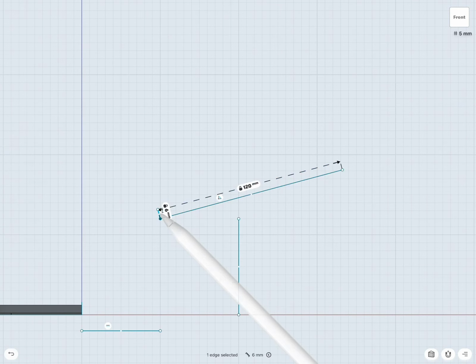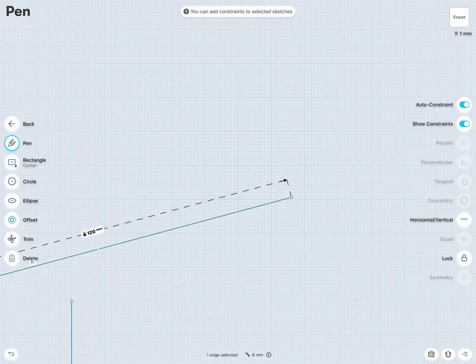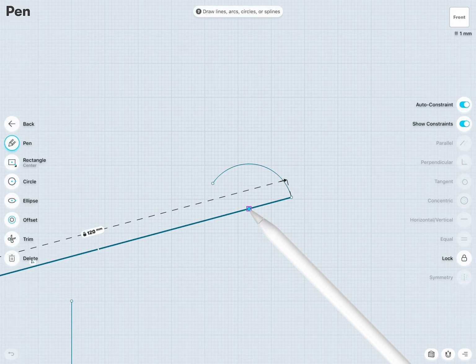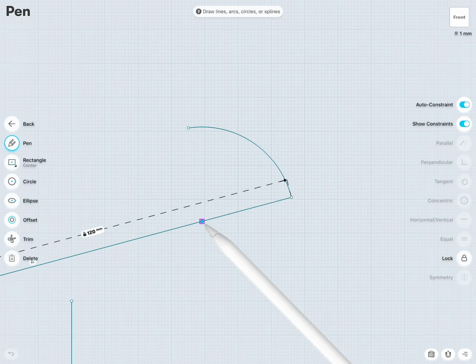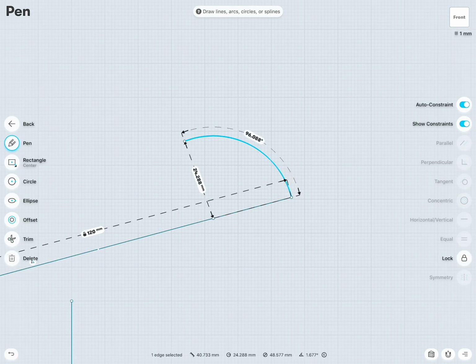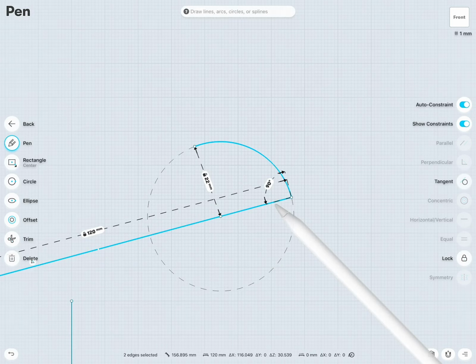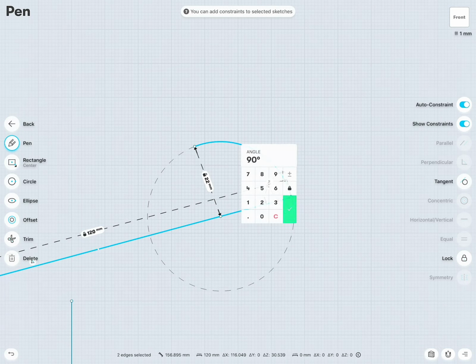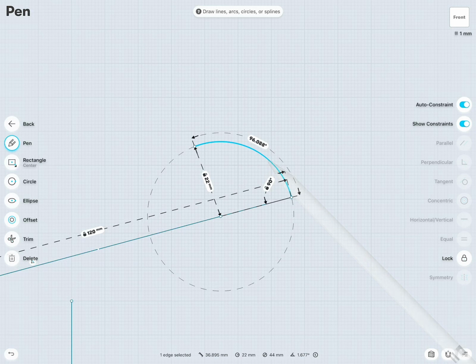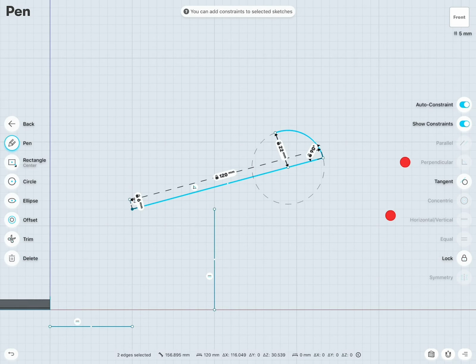Let's make a quick transition. I would like to have a handle and an arc. So somewhere here an arc. This arc center point I want to glue onto this line. So you see I drag it onto it. Now as you can see it has the coincident constraint, which means this point always stays on it. We can also specify the radius. Very good. We can also set here a condition so that actually this arc terminates perpendicular onto this line.